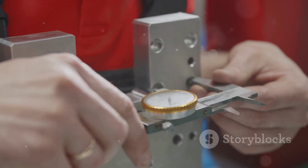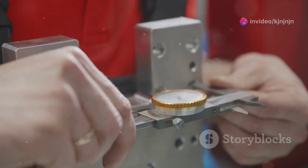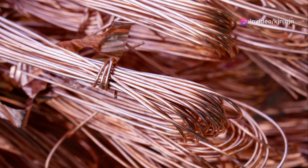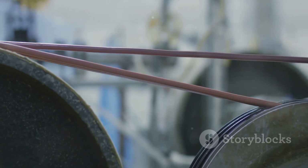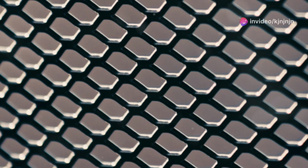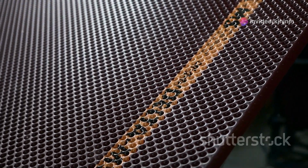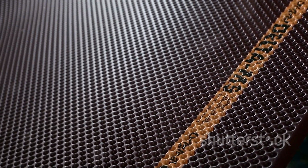The construction of electrical resistance strain gauges is carefully designed to optimize performance. The choice of metal for the grid depends on the desired sensitivity and temperature range. Constantan, an alloy of copper and nickel, is commonly used due to its low temperature coefficient of resistance. The grid pattern is designed to maximize sensitivity to strain in a particular direction. The backing material must be flexible yet durable, providing good adhesion to the tested material.